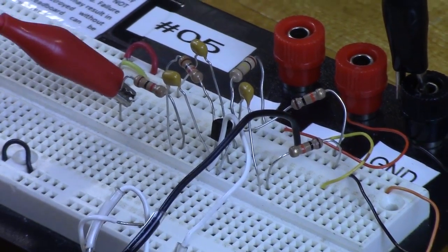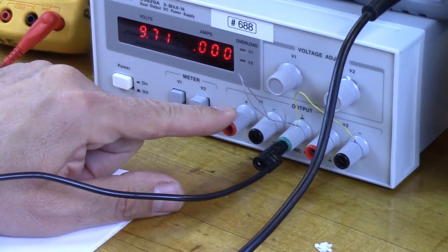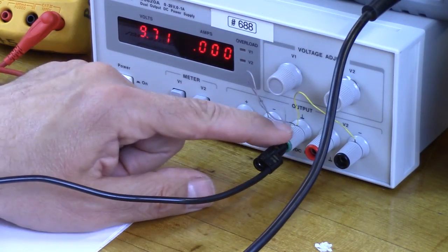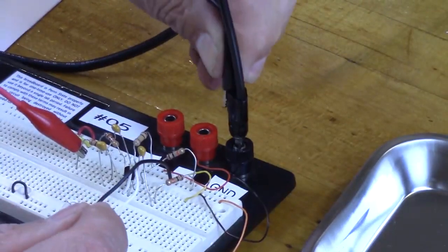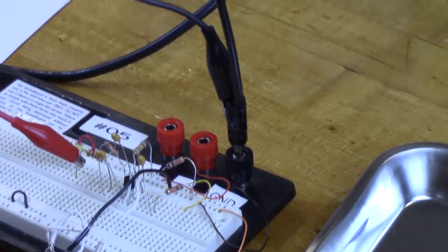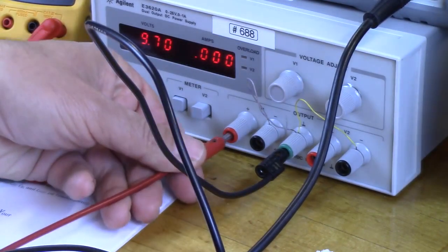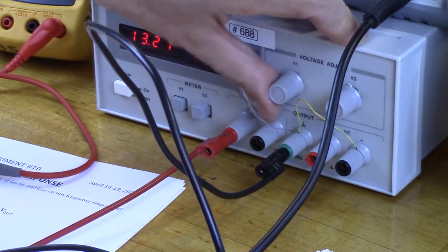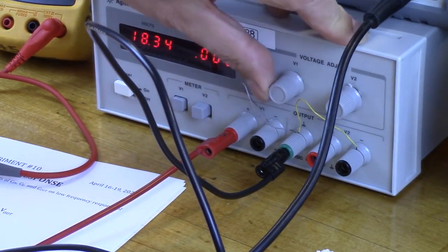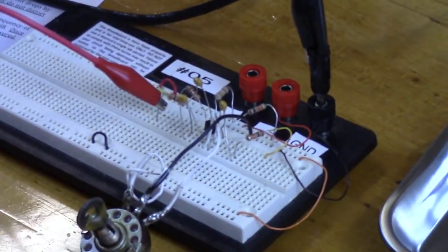So our ground lead, the signal generator, the power supply is already wired for a plus output here on V1. You can tell because the negative is tied to ground. So let's plug that into the ground lug. And then the positive one, we're going to set it before we plug it in. So we're going to set V1 to 20 volts. That is the power supply for this experiment. Okay, and that's going to come over here to the positive lead.